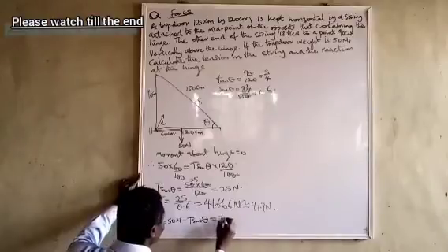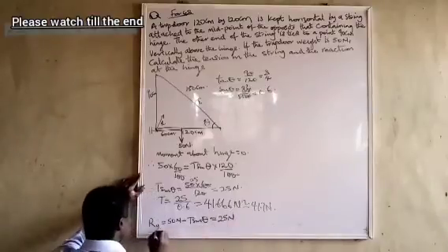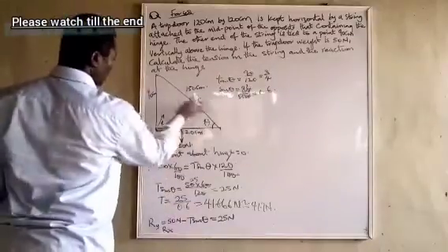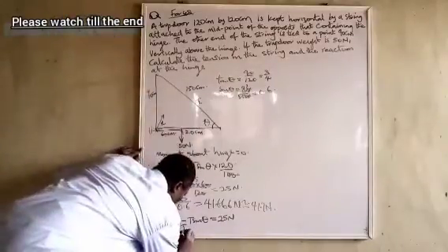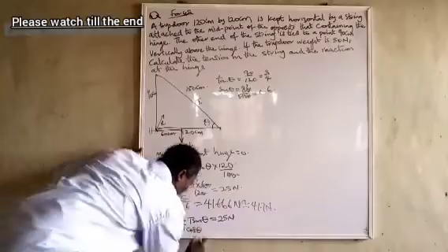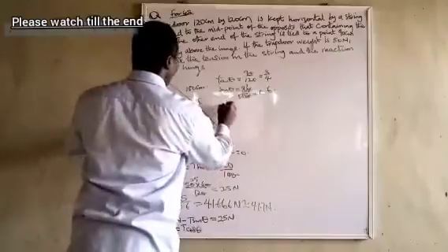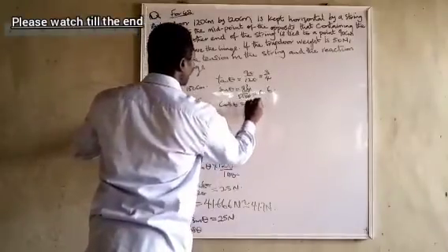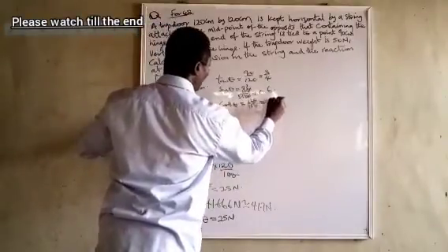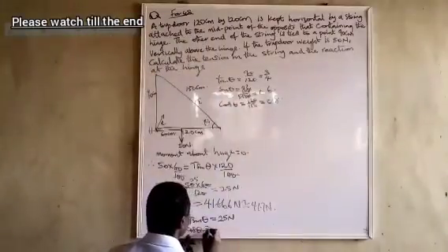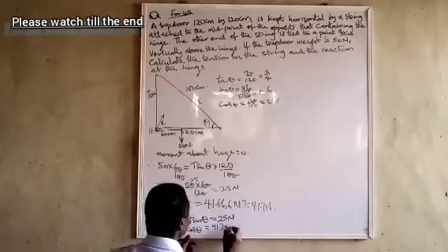So this place will be 25 Newton. And Rx, please, should be equal to T cos theta. And we can easily find that because we know what cos theta is. Cos theta is 120 over 150, which is 0.8. And that will be equal to 41.7 times 0.8 Newton.